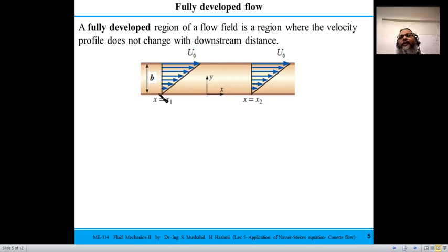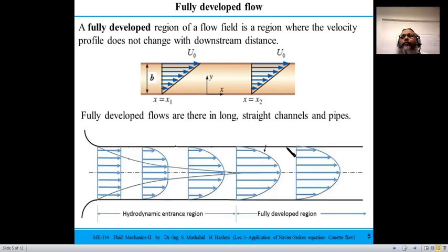After traveling a certain distance, the flow becomes developed, and once it is fully developed, it means its velocity profile is no more changing as you are moving in the x direction, or traveling from upstream to downstream. This fully developed flow is present not just in the fluid flow between two fixed plates, or between one fixed and one moving plate, but even in pipe cross sections.